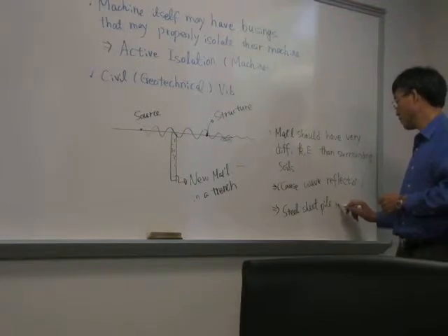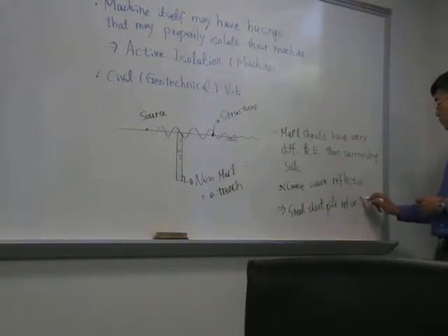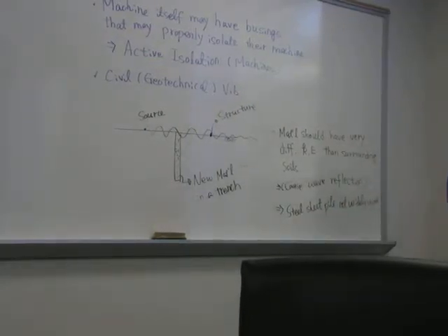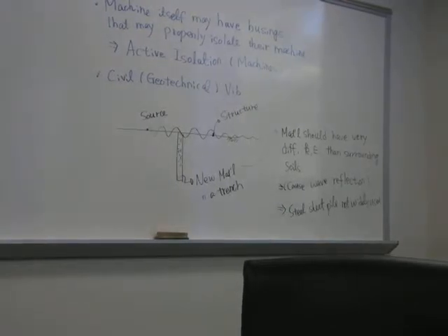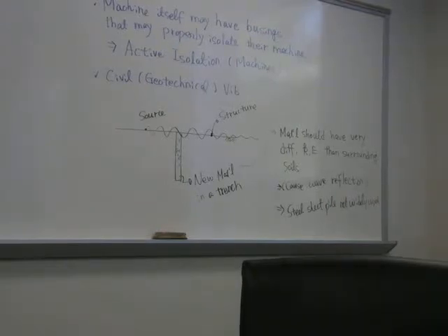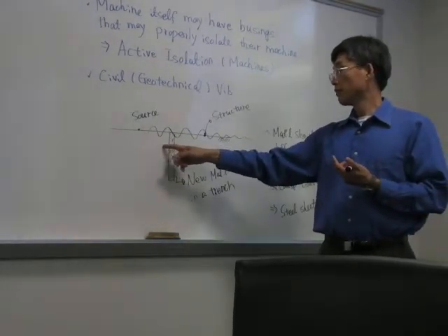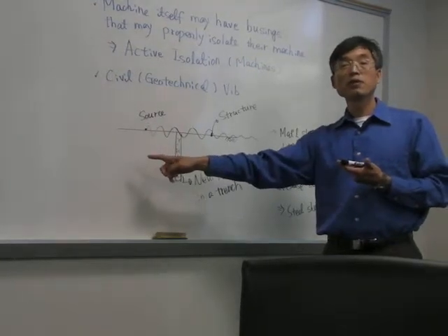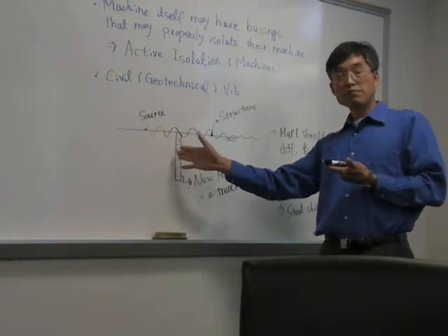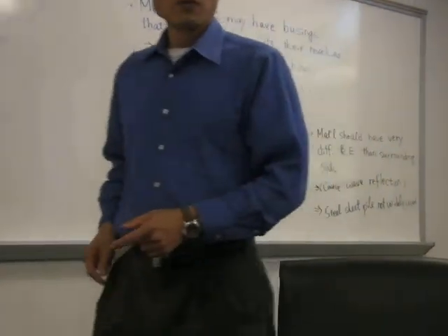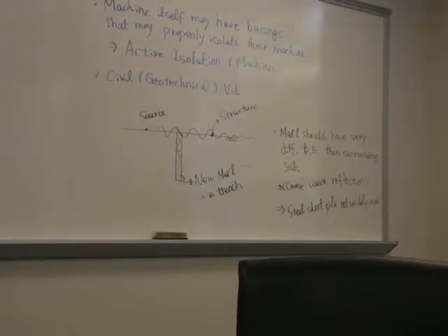This is not very widely used. But it is used. I don't know whether this one was ever used or not. First thing is, it may be a little bit too expensive. Usually steel sheet piles are thin, right? Then they may still reflect the vibration and transmit the vibrations, even though most of the vibrations can be reflected, but when they are subjected to high amplitude of vibrations, then they will still vibrate, and it may transmit the vibrations.